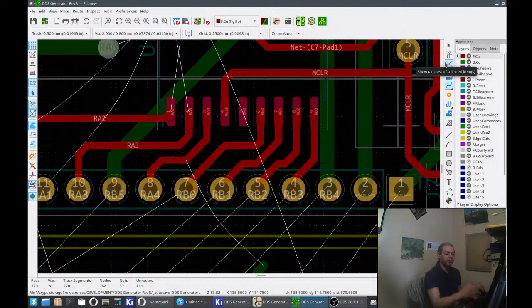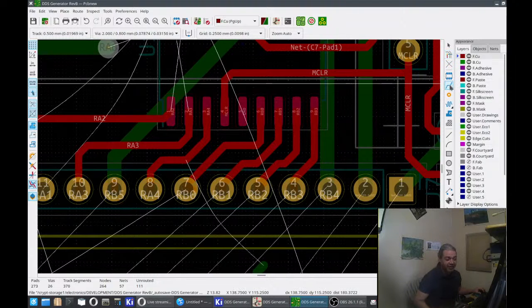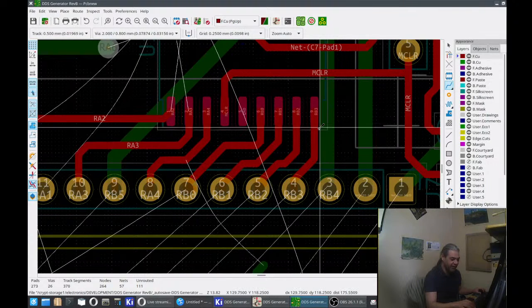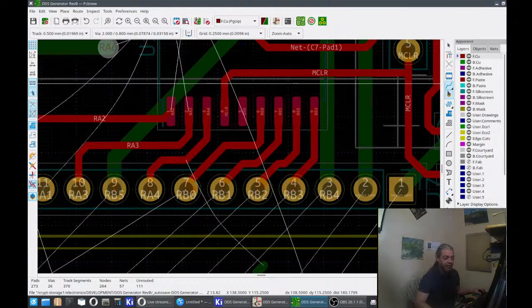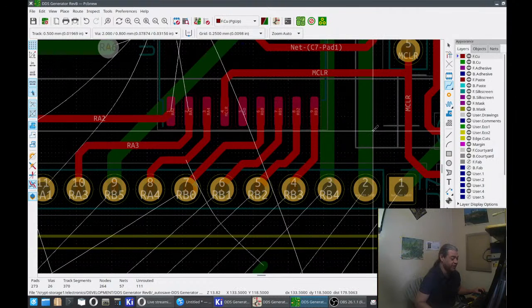So where I'm going with this is, say I'm in track. I touch the track, this is the track icon. I think it should stay in track mode. So if I'm going around pressing delete, it should only delete tracks. It should not highlight other components or pads. It should just be traces. Just like if I select the bulldozer, that should be when you can delete anything you want, right?